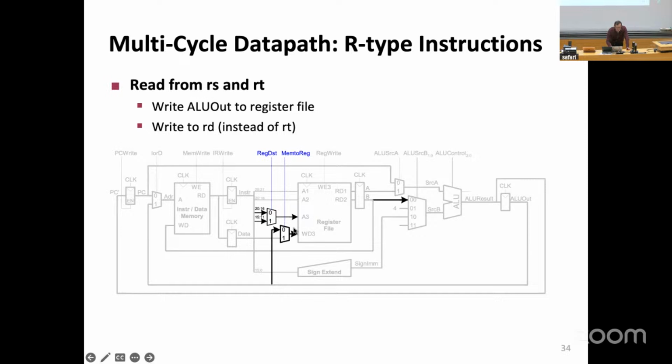So before, we were actually doing something else into the register file, right? This one was coming. Load was loading this data into the register file. So you need to add this multiplexer to decide. And this multiplexer is very similar to the mem-to-reg multiplexer that we have in a single cycle design. If you remember, you either take the ALU output and put it into the register file, or you take the memory output. It's essentially the same multiplexer that you have, except it multiplexes between this register and this register, okay?